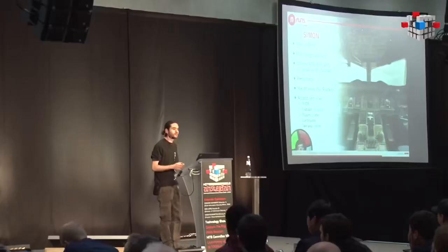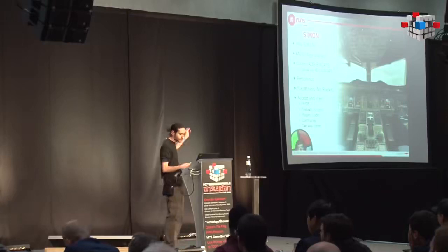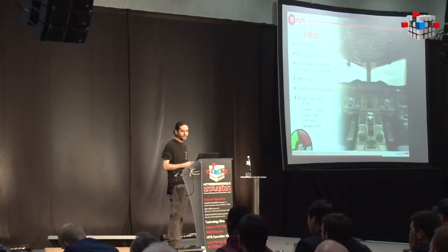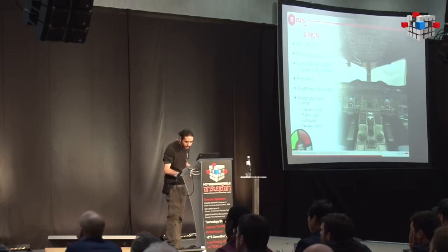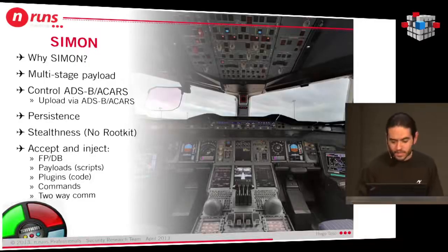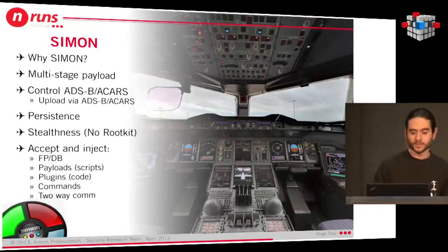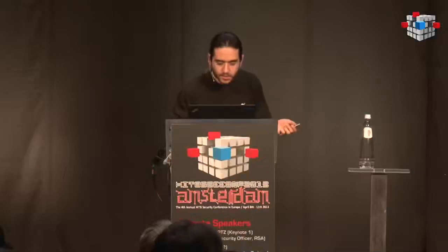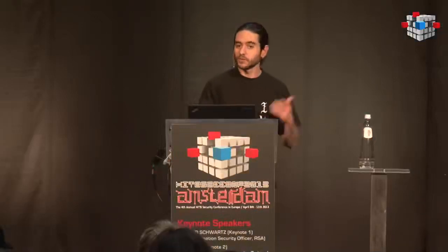This is, for example, the A380 cockpit. Please point me to one older analog system you can rely on, like a compass, an attitude indicator, an HSI, something. You can see maybe here one. Come on, you see that? This is a keyboard and a touchpad. This is not a control column. This is a heads-up display, and you don't even see the control column. It's over here, and it's a side stick using fly-by-wire, another computer. So there is little you can trust.